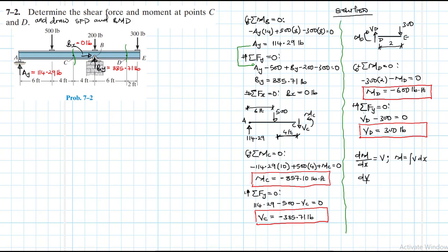The rate of change of shear with respect to x is equal to distributed loading, and the shear itself is the area under the load diagram.